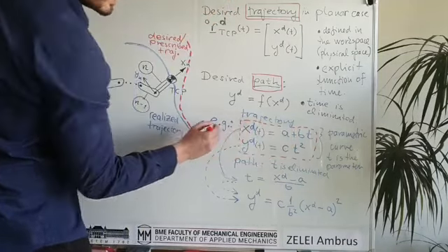Of course, if the lengths are the same, you can reach this point also. But if, for example, L2 is shorter, then you can just reach a certain distance from the origin. So finally, this will be the shape of the set of points which can be reached by the tool center point, and this is called workspace.